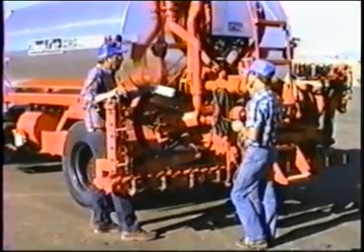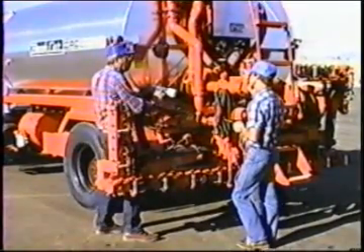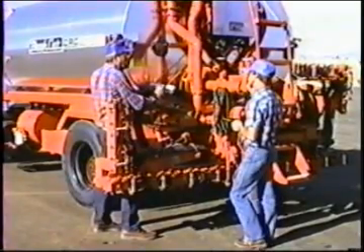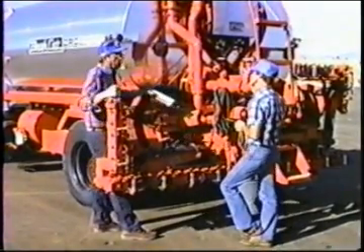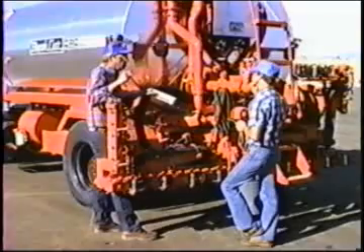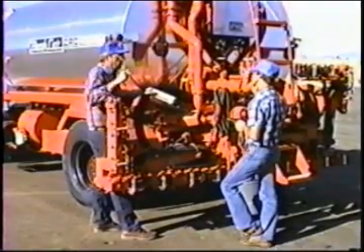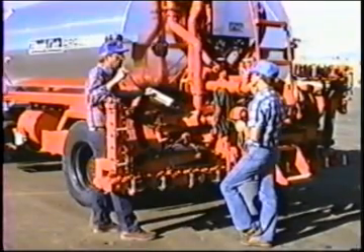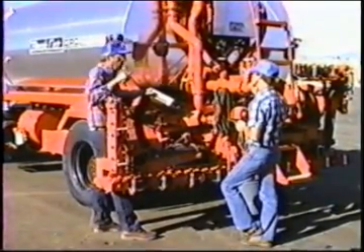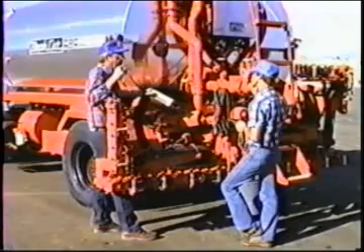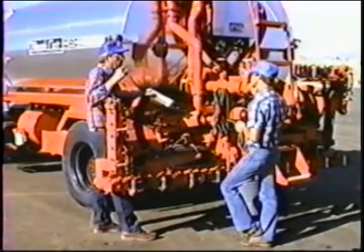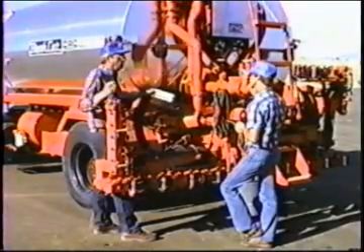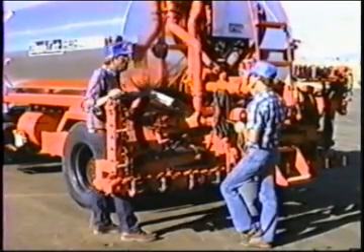Anytime we make a setup like that based on this chart and based on the engine tachometer, neither of which are extremely accurate, we want to double check our setup. That is, just as soon as we start spreading, go to the set speed. That is, we set up at 400 feet a minute. That's the speed we know the number for. Go to that speed and see that the pump is turning 135 gallons a minute when we're at that speed and that bar width, the 12 feet wide. Just double check it there.